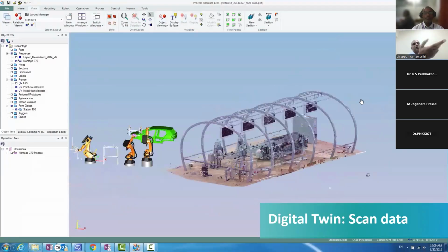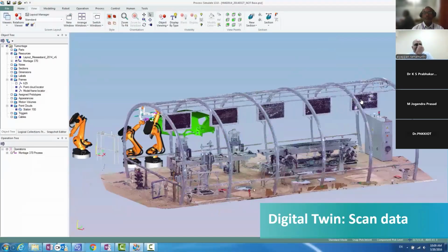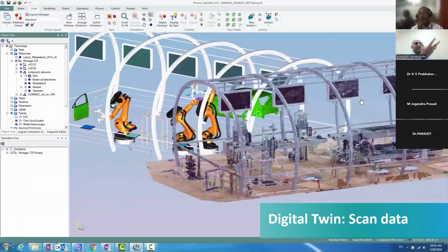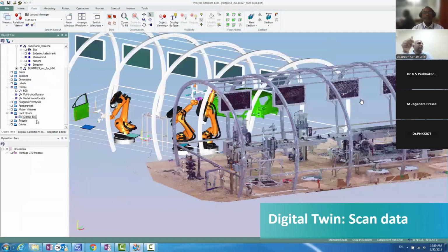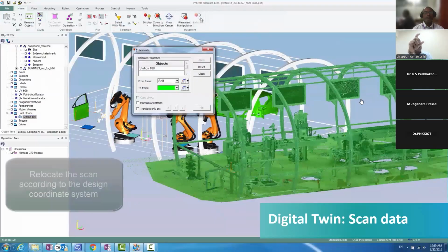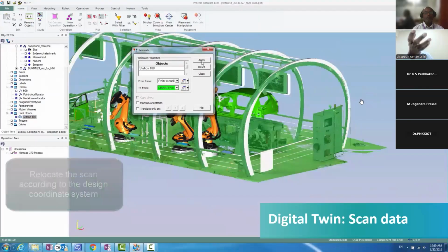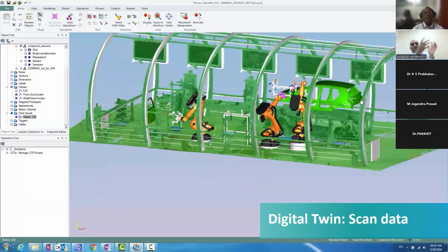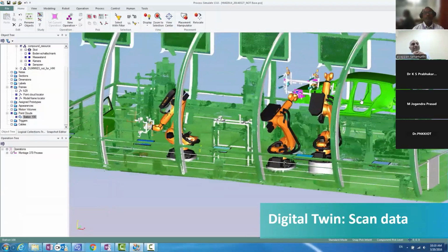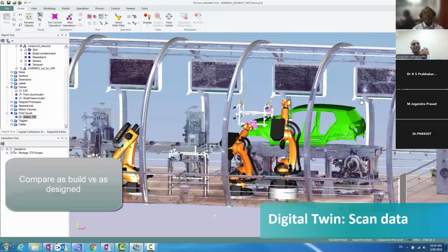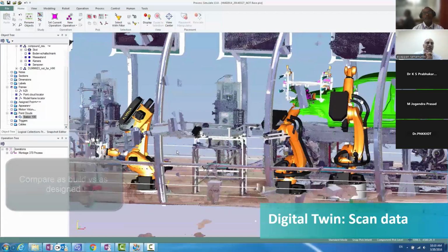And to bring in the digital twin, you can use the scan. The reason why I am displaying this is, you can create a digital representation of the factory, but you can use your phones to take photos from multiple angles, and there is software which can take these photos and create the point cloud model. So you can use a white light or laser scanner, but you can also use pictures to create the models, so you have a digital representation of the factory available.